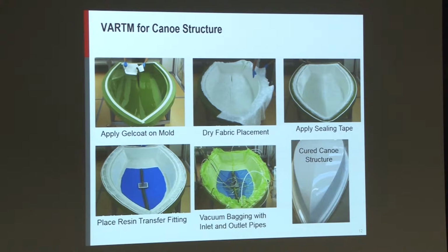Now, a couple of things here. The curing of polymers, resin, is generally very exothermic. That means it generates a lot of heat during the curing process, and depending on the shape of the structure that we are interested in, there could be excess stress concentrations that could damage the material during the process itself. So it's very important to account for the heat generated in the presence of pressure and the shape of the component itself.